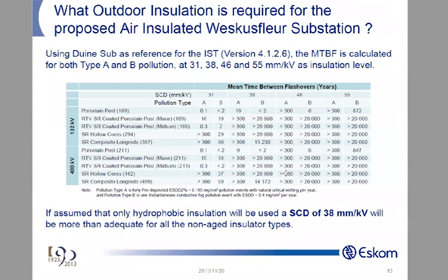Well, let's think about this. Okay, bare porcelain, pollution layer, nice and thick. Does the pollution layer interact with the porcelain? No, it's inert. Now, is there any way you can improve that? Well, you'll have to wash it off to get the area as small as possible. But now you wash it off, and now it's back again.